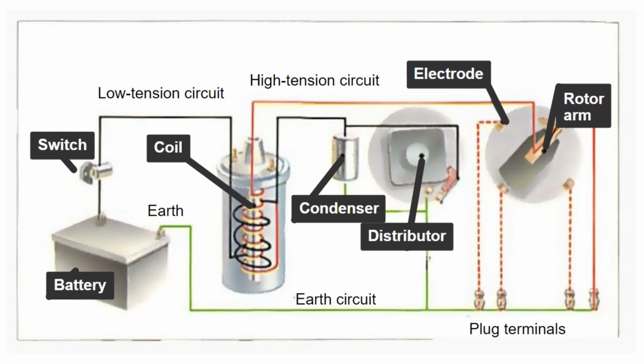The spark occurs many degrees before the piston arrives at top dead center. The contacts are run by a shaft controlled by the engine camshaft, or the timing of the pulses is controlled by a sensor on the engine shaft. Whenever electronic ignition is used, the amount of energy in the spark needed to ignite the air-fuel mixture changes depending on the pressure, the mixture, and the speed of the engine.